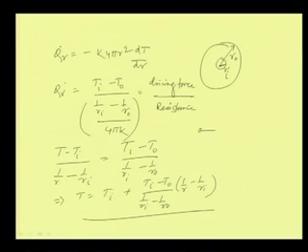If we see that electrical analogy, this is T_i, this is T_o, and you have this resistance, and we should be very careful about the resistance term, (1 by R_i minus 1 by R_o) by 4 pi k. So, this becomes the resistance of heat transfer in a hollow spherical body from R_i to R_o, when the thermal potential at R_i is equal to T_i and at R_o is equal to T_o.